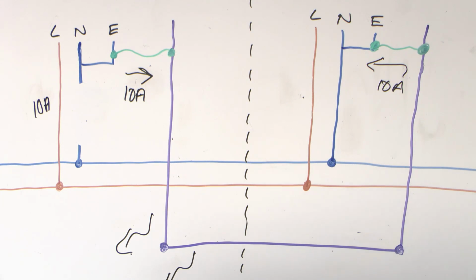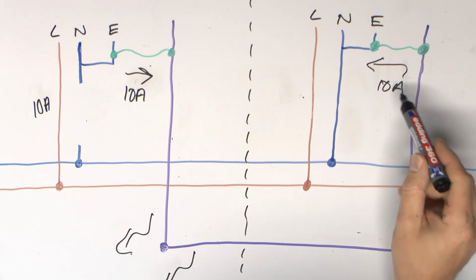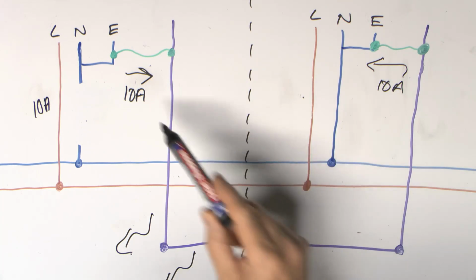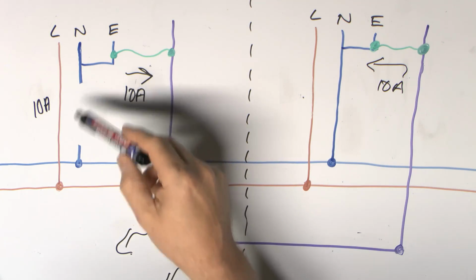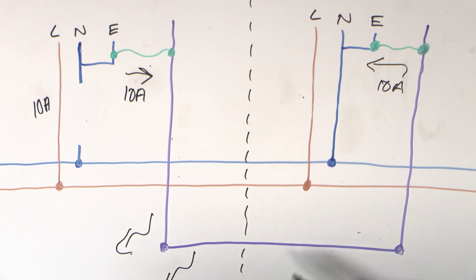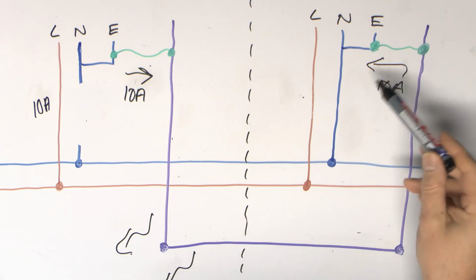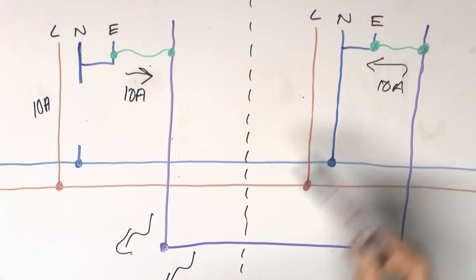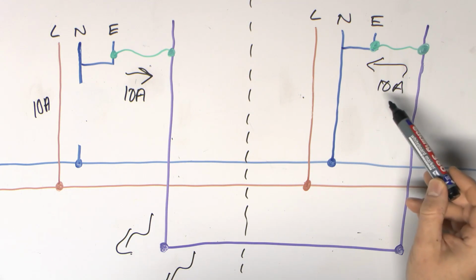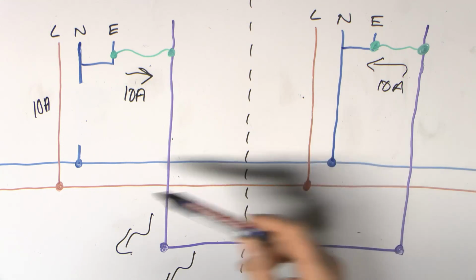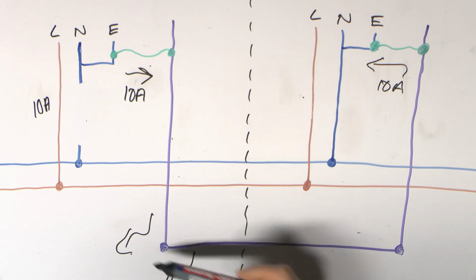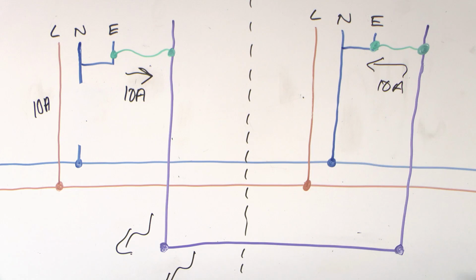And here's where the real problem is, in that you can't tell where this current's coming from. It might be coming from next door in case of some faulty part, or it could be just earlier that we saw that because you've got parallel paths, you're going to have some sort of current there anyhow. But generally, the larger this current is, the more likely it is that something has gone horribly wrong, and in this case, it's effectively the whole load current of that piece over there.